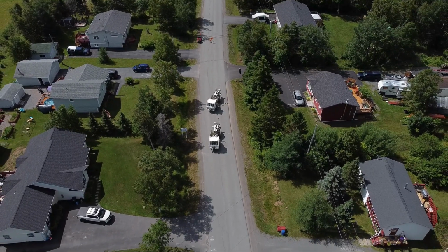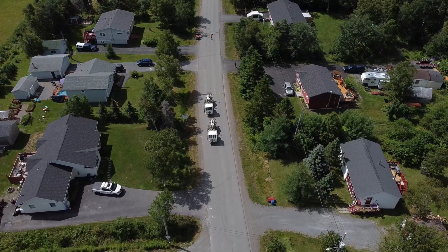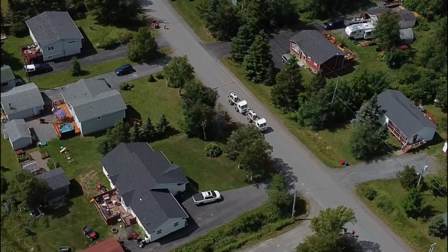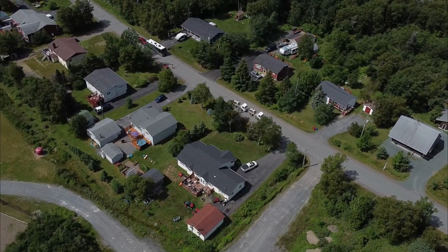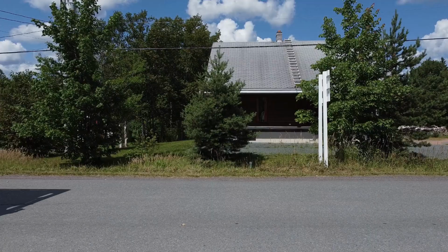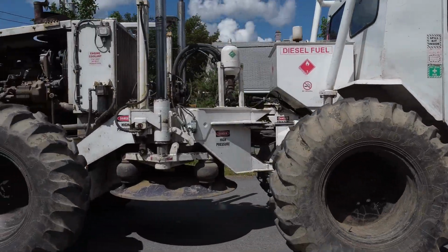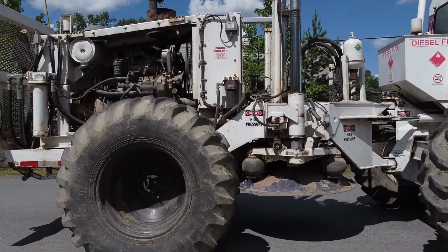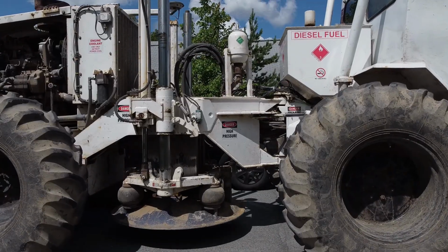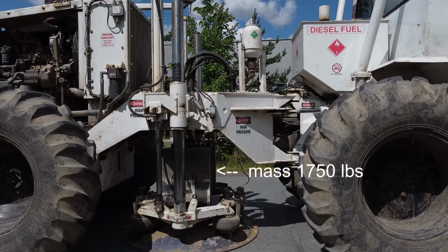A lot of this will be focused on seismic vibrators, but dynamite settings are essentially the same. The main difference is vibrators are generally a longer but smaller energy event, and dynamite sources are instantaneous. I also plan on creating short videos on sensor coupling and orientation, setting up a test program, reviewing, analyzing, and displaying the data, and how we used vibration test monitoring to change the geophysical distance requirements from specified structures in Alberta.